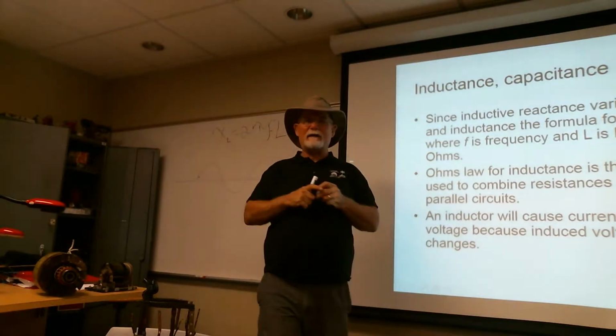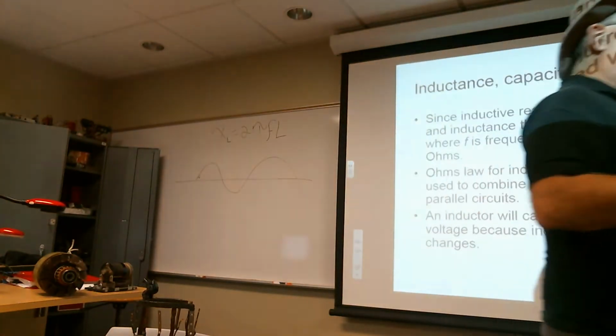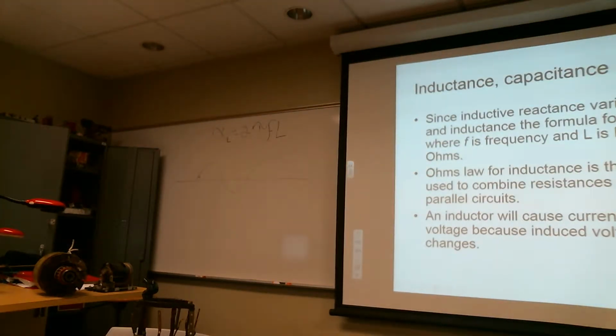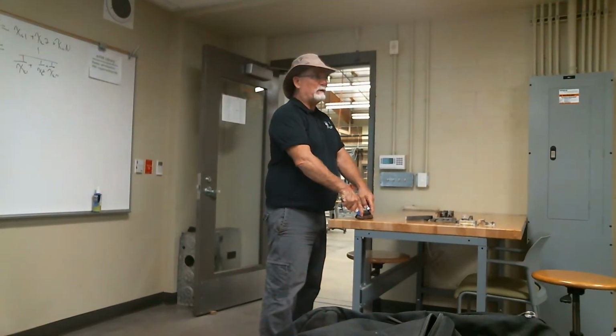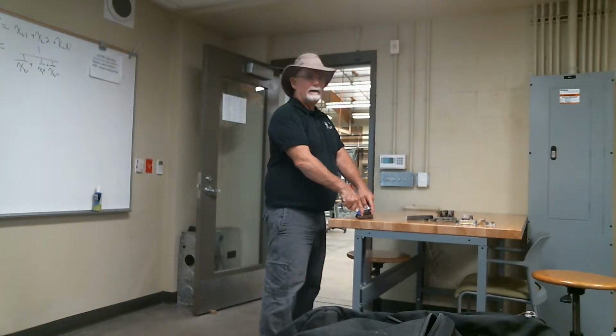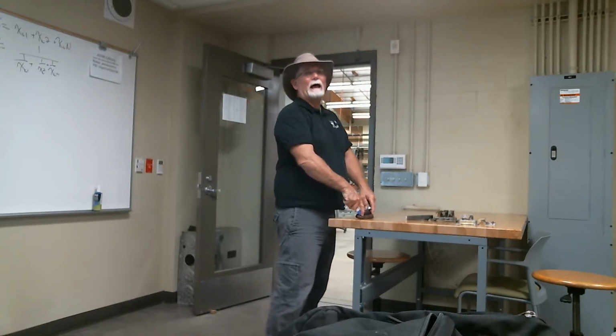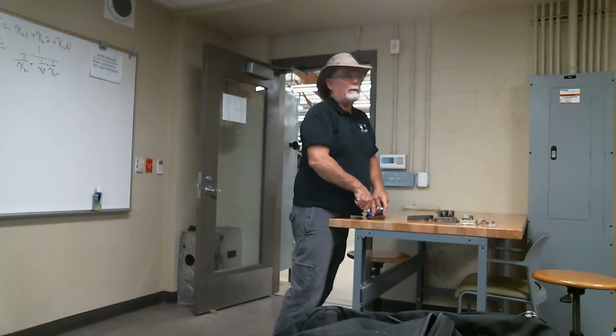Okay, if I look at that voltage, when I take the power source, I am the human power source, and I attach it to the coil, what happens? Well, immediately on both sides of the coil, I've got voltage applied, right? The current starts flowing, but magnetic field has to build up, so it lags. It slows way, way, way down.